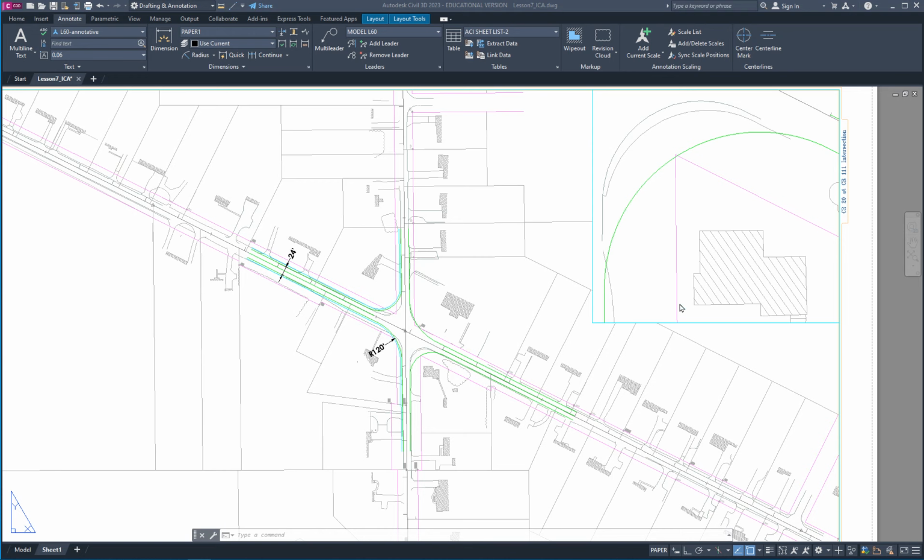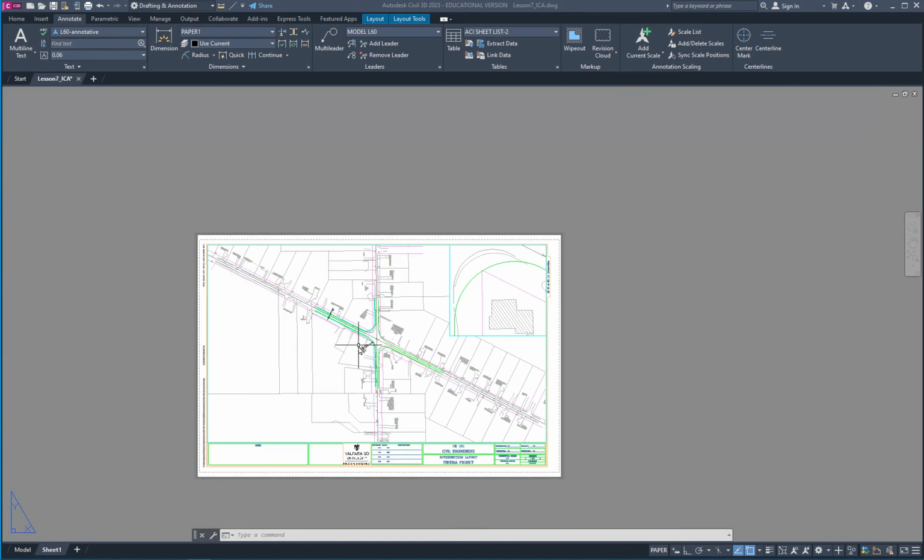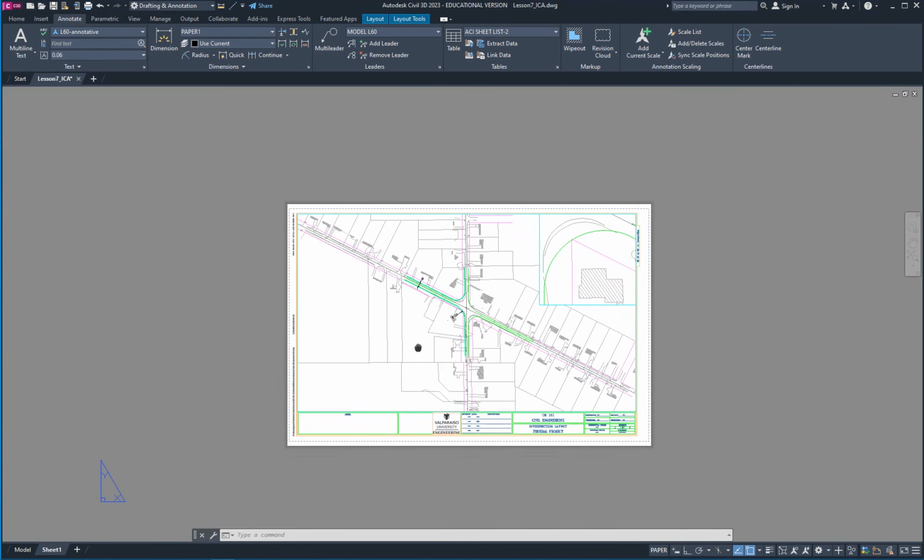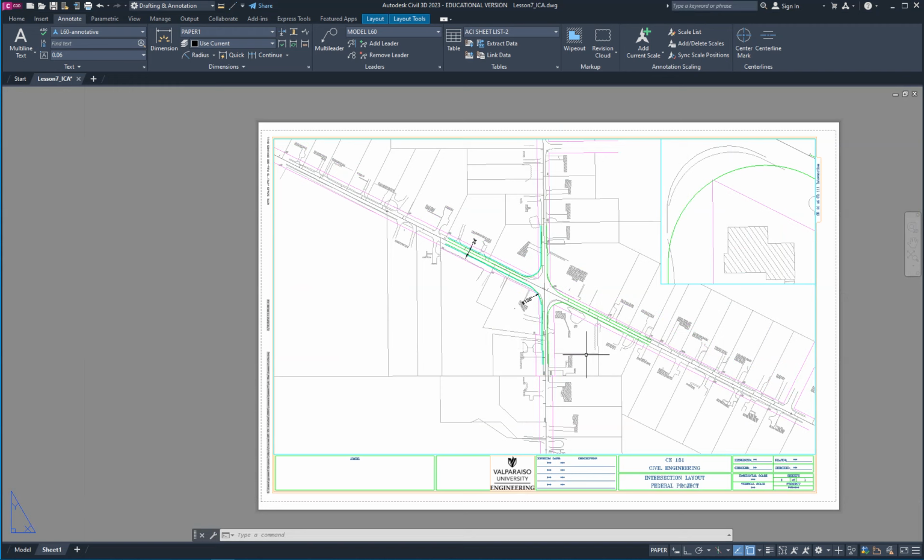When you do the homework then, for today, you're going to do the last homework you did, which was redesigning the computer lab. But you're going to now make a file that just has the outlines of the walls on it. And then you're going to use that as a reference into a design drawing that you're actually going to draw in all the little tables and chairs and stuff in, or the desks in there, move around. But the wall shape, the wall outline will be in an Xref file, right from that. I think that covers all the basics for doing this Xrefs.